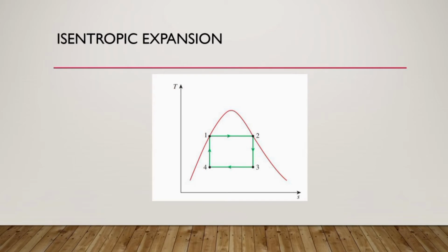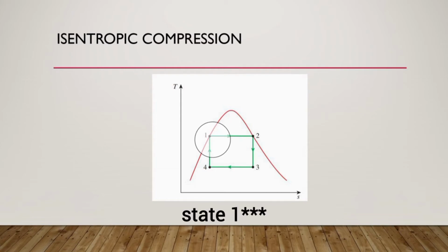This can be overcome by using a working fluid with a very steep saturated vapor line. The two-phase liquid vapor mixture from the condenser will be received by the pump. Supposedly, to compress the liquid vapor mixture to its initial state, the process has to occur isentropically. However, it is difficult to associate the process with the idea of an isentropic compression process. This is because it is not easy to control the condensation process precisely to achieve the desired quality at state 4. Besides, a pump is practically designed to handle liquid only.